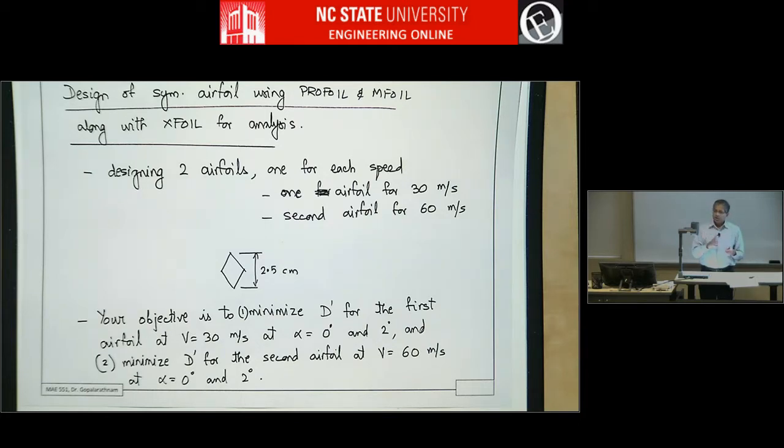But although it is nominally at 0 angle of attack, the airplane is going to be having side slip and some perturbations, and it's going to be doing some maneuvers. So you don't want an airfoil that's really optimized for 0 degrees, and then at like half a degree angle of attack it just causes some huge drag increase, right? Because nothing is going to operate perfectly at 0.